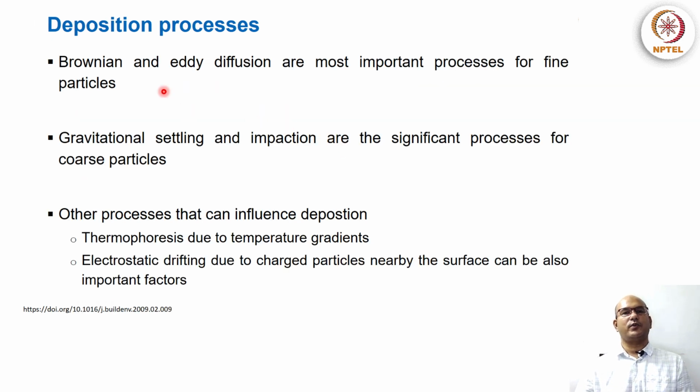In general, Brownian and eddy diffusion are the most important processes for fine particles. For coarse particles, we are looking at gravitational settling and impaction as the main processes influencing their deposition. Then there are other processes in a regular indoor environment that can also influence it, one is thermophoresis, so temperature gradients within a room.